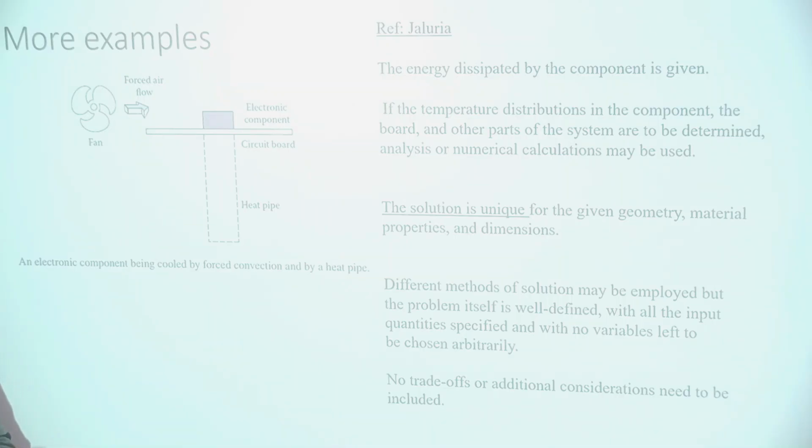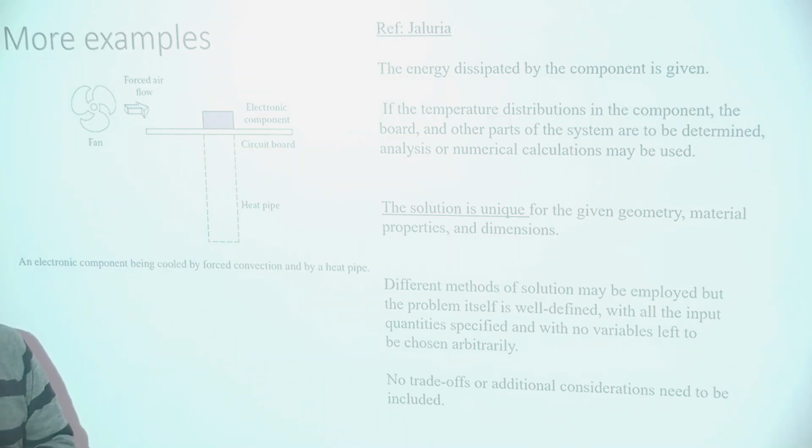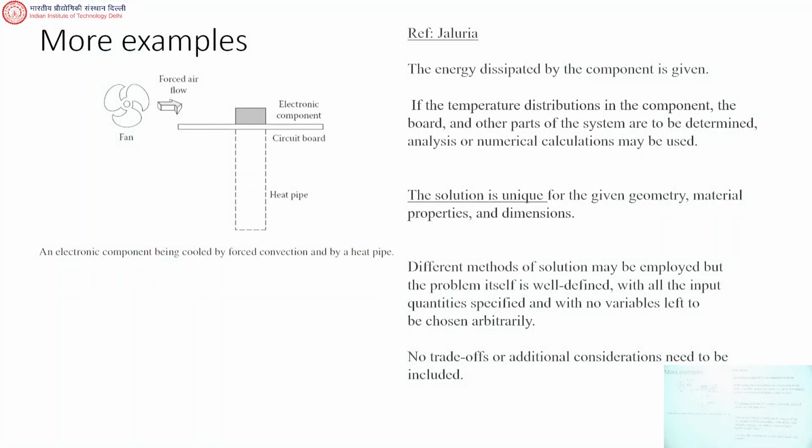The electronics person who is working on this will give you the heat dissipation from here, so many watts. These are like small components, isn't it? So you have to make sure that it's less than 80 degrees Celsius. If you can do that, then your job is done. But then also, since it's a design problem, less than 80 degrees Celsius can be achieved by some of you with different choices of materials and fans and dimensions and all that, right? So there also there can be variability.